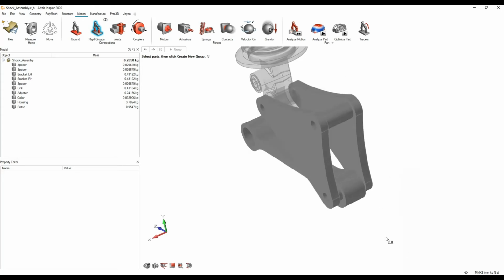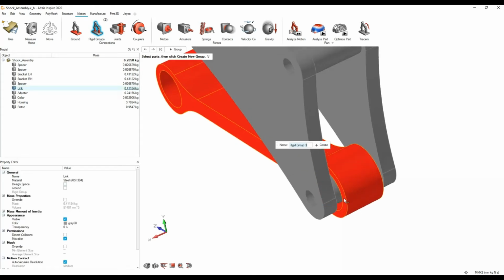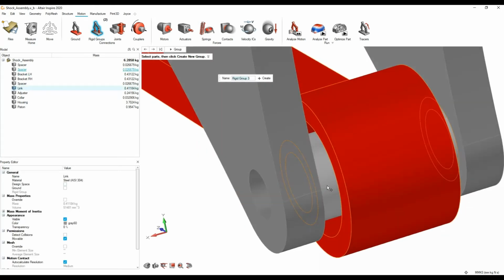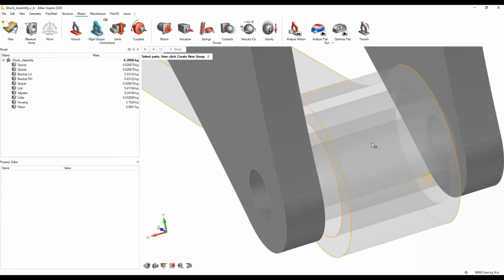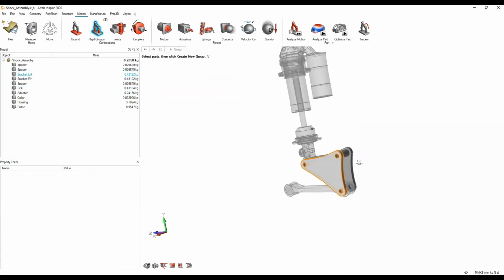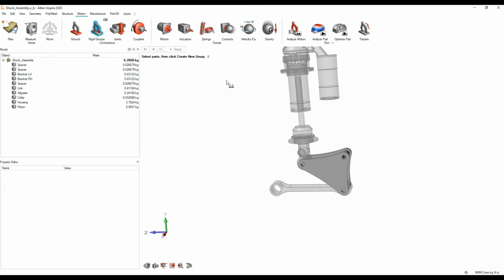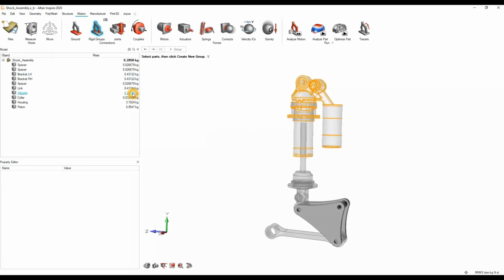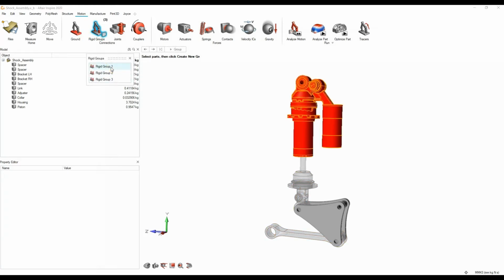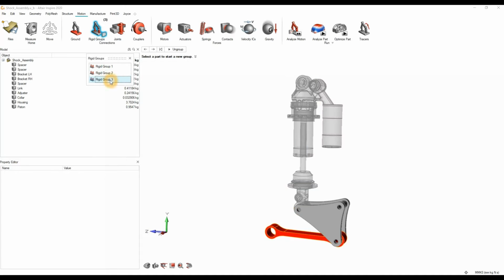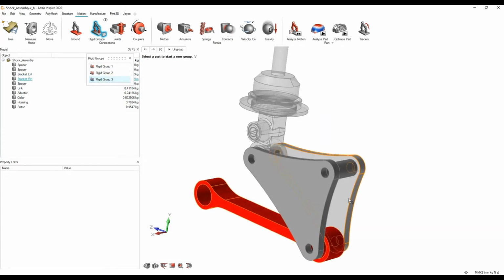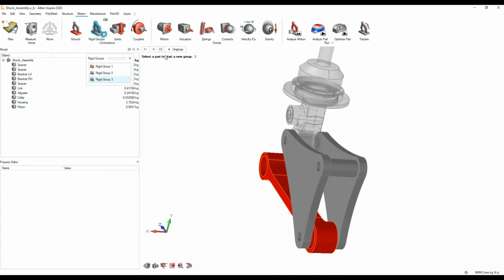And what we also want to do is make sure we have this link with this other internal spacer down here as another rigid group. So all in all, we have 3 rigid groups. Now for anyone who doesn't know what their groups are, or whether they've done it correctly or not, at the bottom of each button down here you'll see a table icon, and through this you can review exactly what your groups are. If you need to edit it again, you can always ungroup and regroup them to create it again properly.